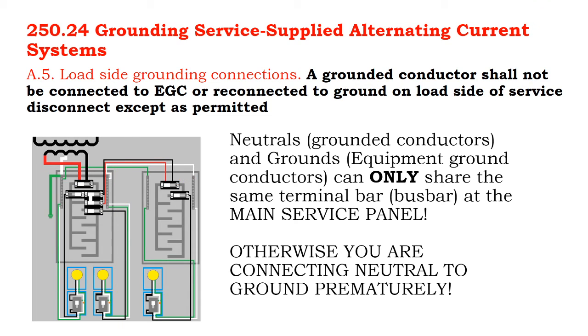But we're not doing it here because this box is actually off a sub panel, and in that sub panel, they already have a neutral to ground connection. So that's the main rule of thumb: when you have sub panels off a main panel, don't put the neutral to ground in the sub panel. If it's a standalone supply side tap service, then you can do it there, but not off an existing service. You only want to have one neutral to ground connection.